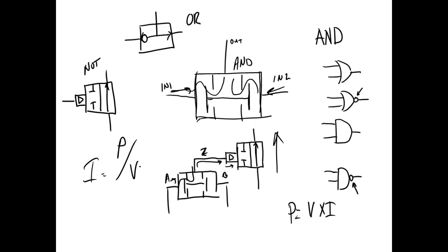So what you do is you take the diameter, divide it by 2, square that, multiply by 3.14. The bore, if they give it to you in square inches, that means you don't have to do anything.